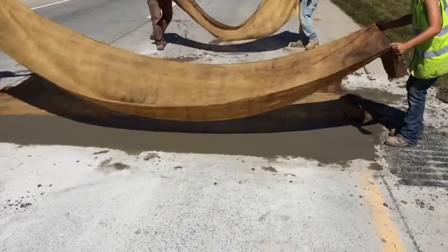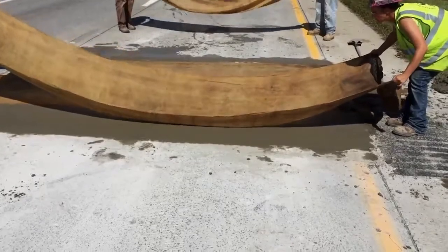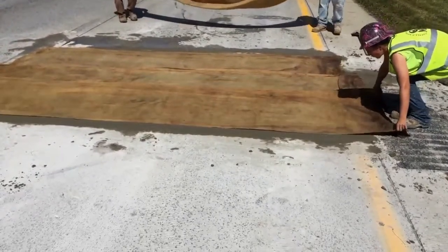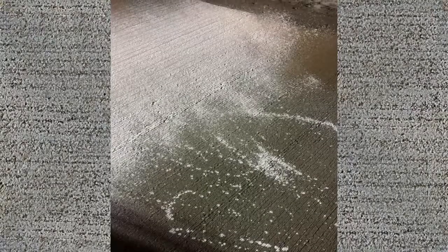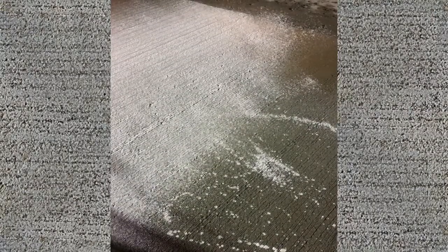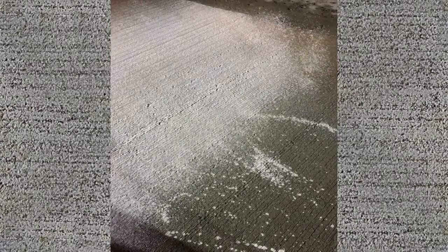Curing of concrete. Normal strength. Apply cure immediately after the completion of the finishing operation. Apply either wet burlap or white pigmented spray cure at a rate of 150 square feet per gallon.